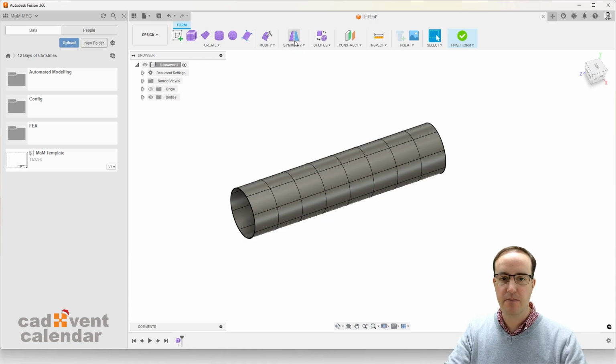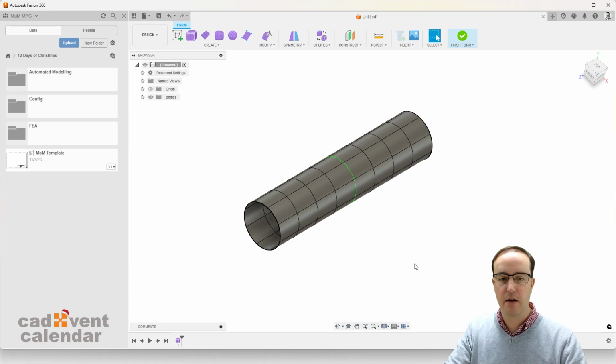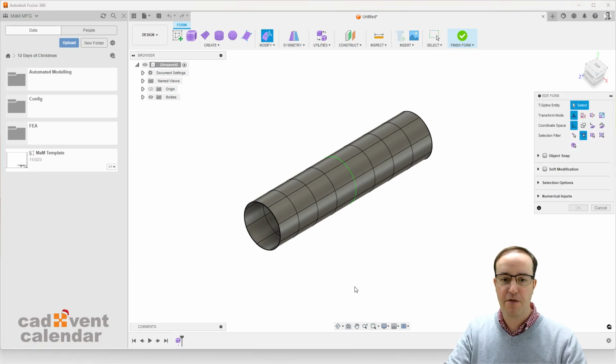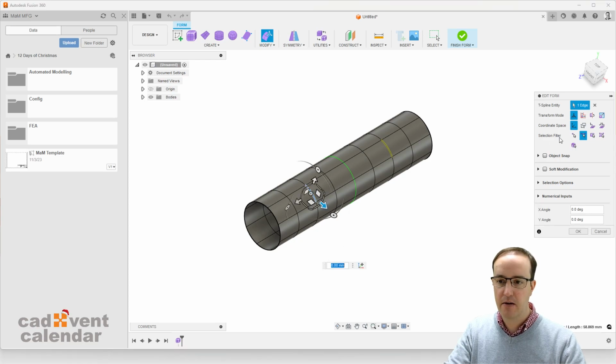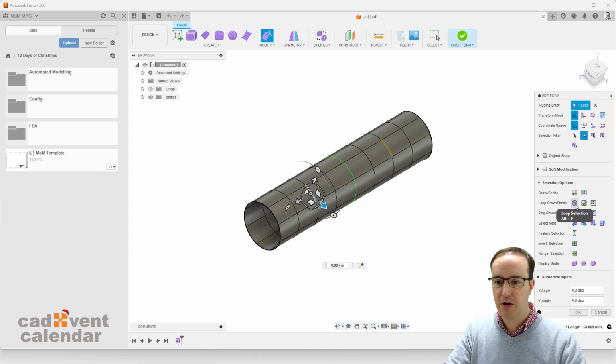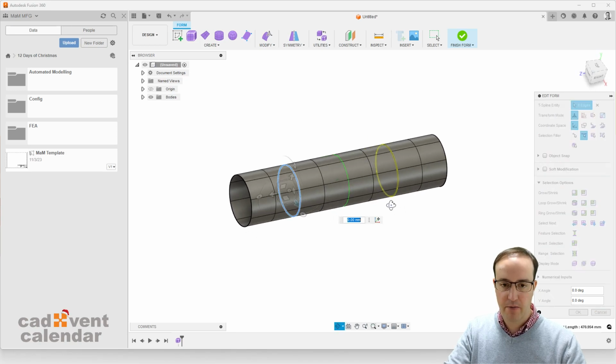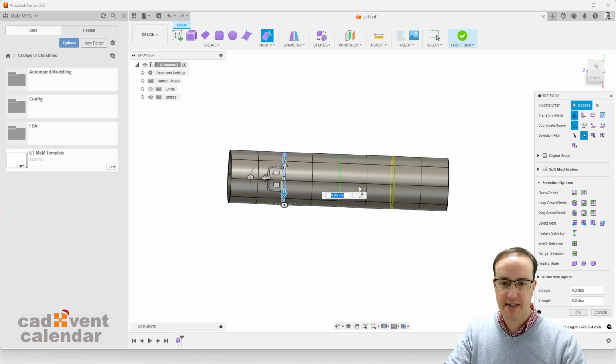I'm going to turn on some symmetry, and I want to choose 2 faces that are symmetrical and click OK. This puts a line of symmetry around this particular component. Then using my modify tools, I can either grab edges, faces, or vertex to make changes. So I'm going to say that I only want edges. I want to select this edge just here. I want to use selection options to loop that edge around. This is what I have selected, and this is the symmetrical side.